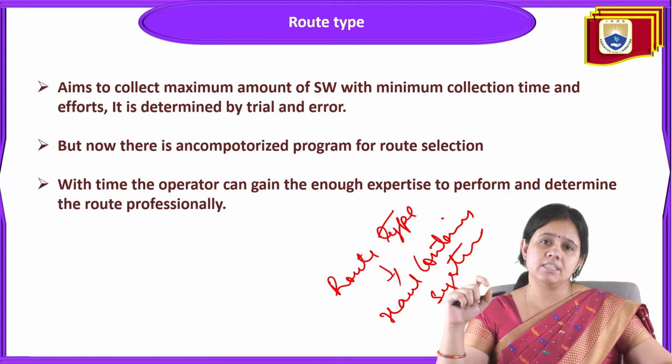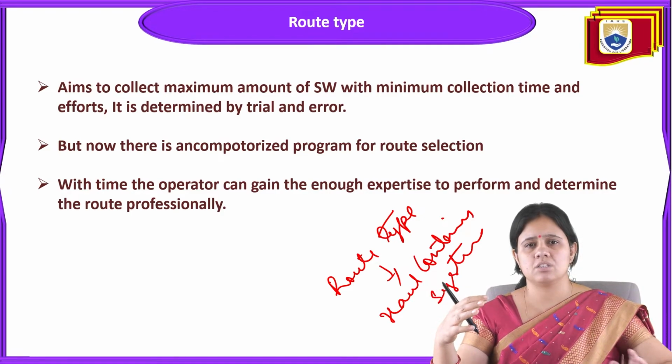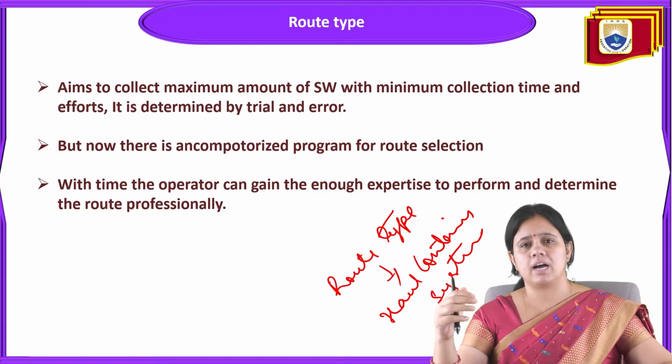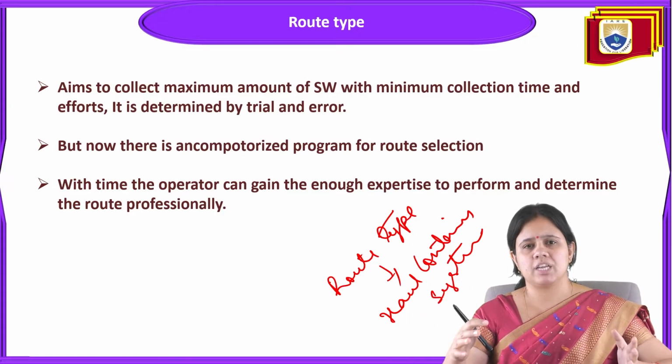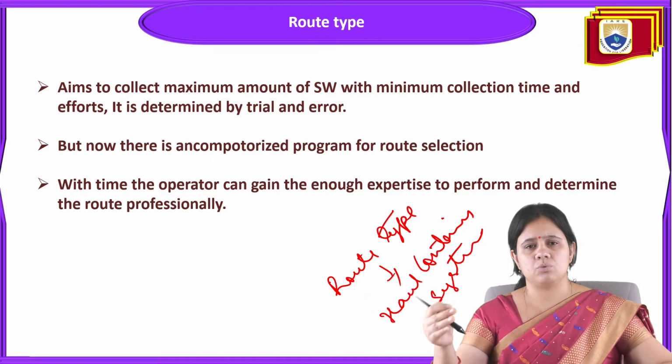Or if the storage is in the middle of the city, then this type of condition should be avoided, because it is not aesthetically good. So it is better to keep this haul container system either in a less dense population area, or sometimes outside of the area, or the route should basically be highways only, not a narrow road or any colony or any municipality type.